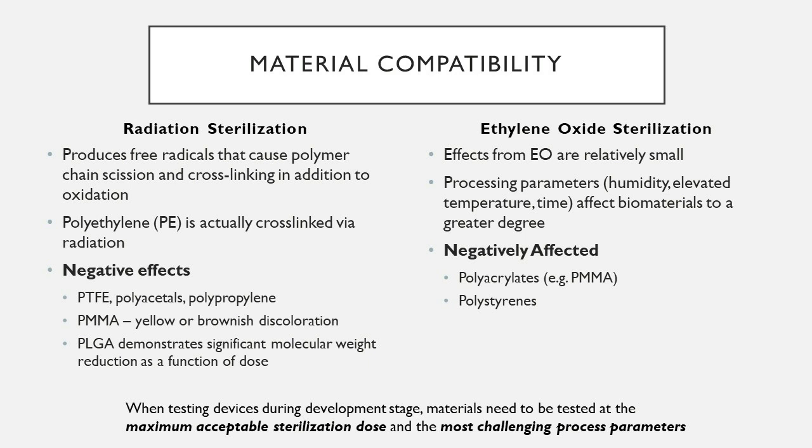Now, as I alluded to at the beginning of this chapter, sterility isn't the primary objective from a biomaterial engineering standpoint because it's easy to achieve, and if that was the only thing that we were concerned about, we could simply have much longer radiation cycles or ethylene oxide cycles in order to achieve what we want. The main concern from our perspective is material compatibility. So this will tie into a lot in the degradation of materials chapter that we're covering as well.